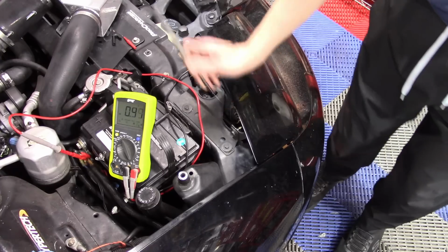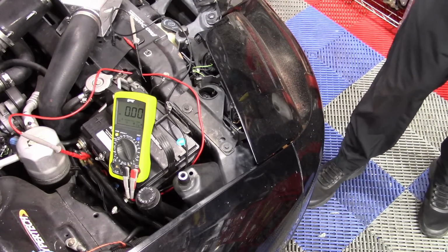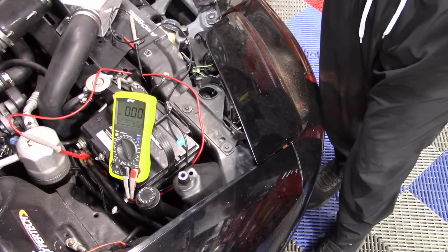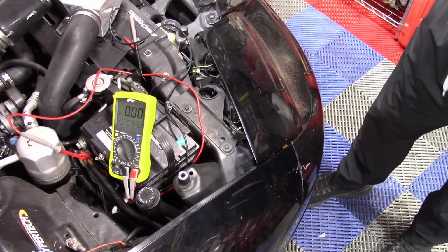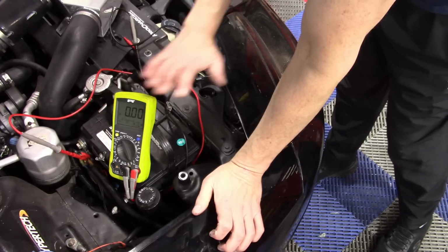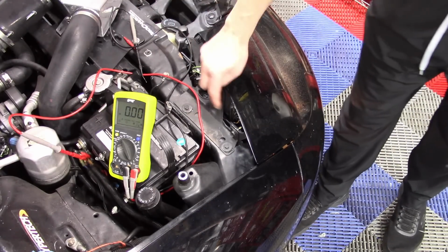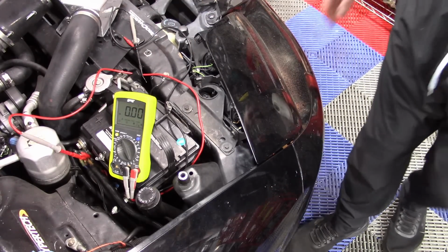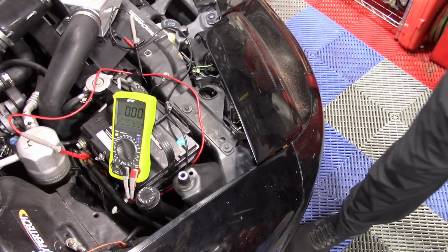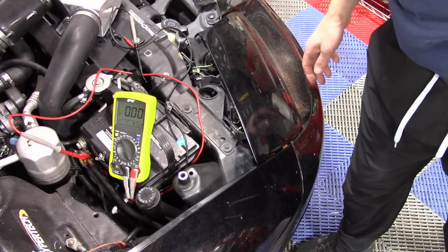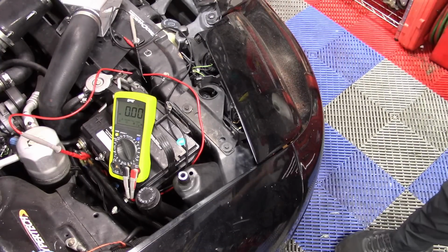By the way, did you notice Kirchhoff's law again? If we add up our 0.91 and our 0.13, it adds up to the exact voltage drop that we measured. The sum of all voltage drops will equal the source voltage. So on this car, I really do need to replace the wiring for this headlight on the positive side, if nothing else, because we are losing a volt on the positive side.